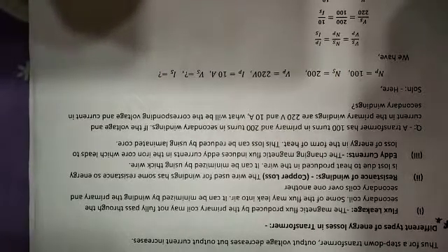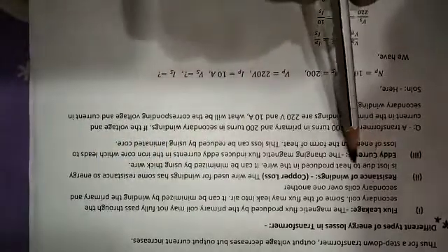The second energy loss in a transformer is the resistance of the winding, which is known as copper loss. For the primary and secondary windings we use copper wire, and when current passes through the copper wire, it offers resistance. As a result, heat is produced in the wire. So the wire used for winding has some resistance, and energy is lost due to heat produced in the wire.